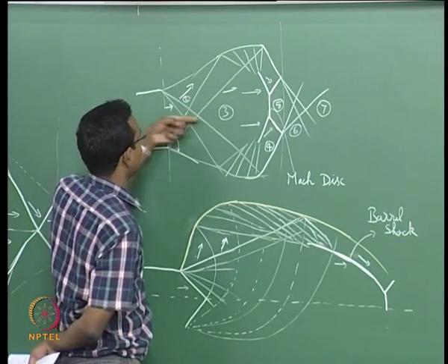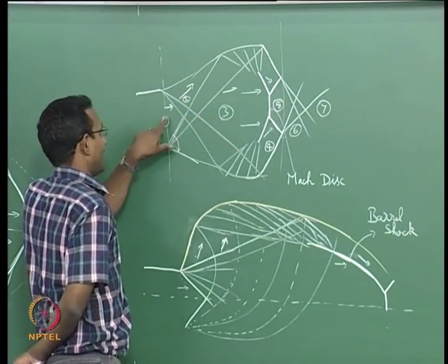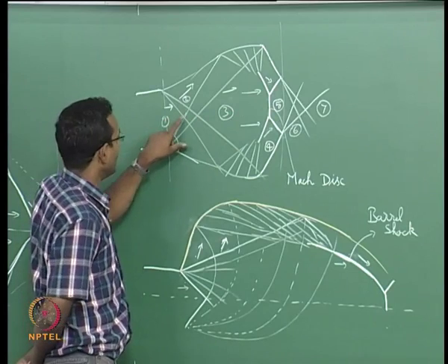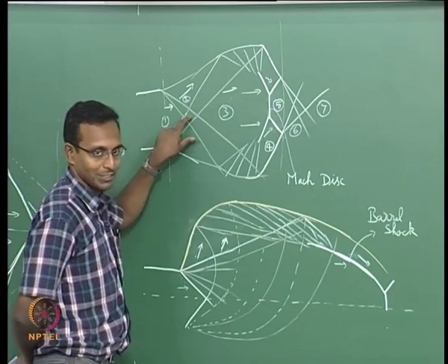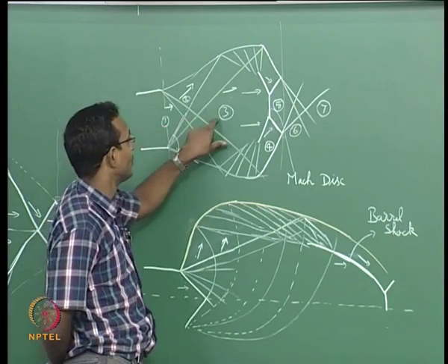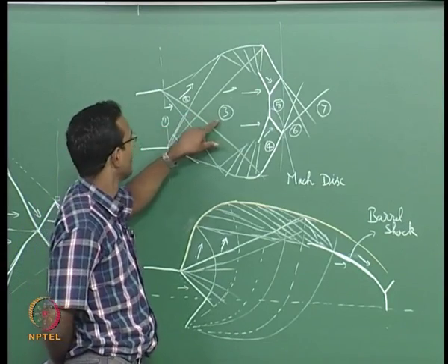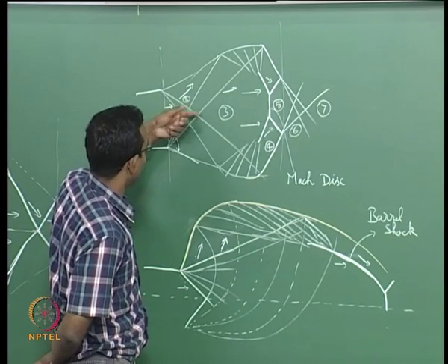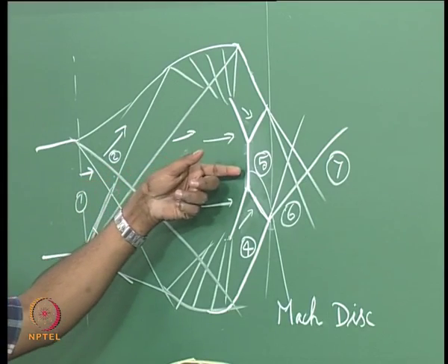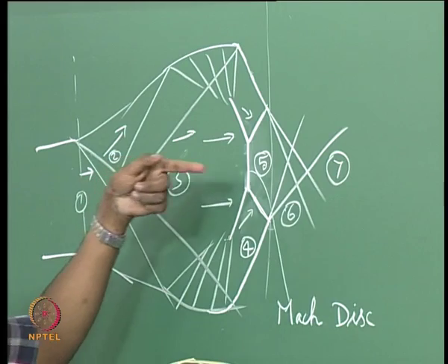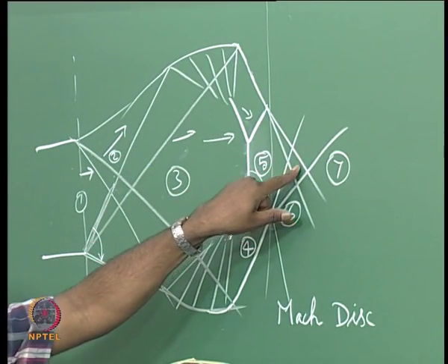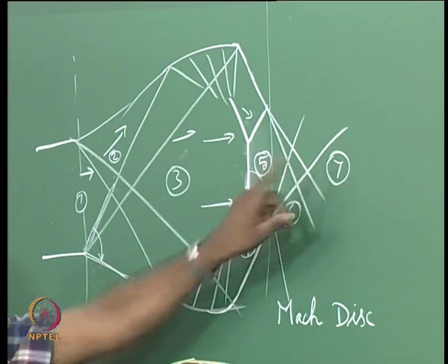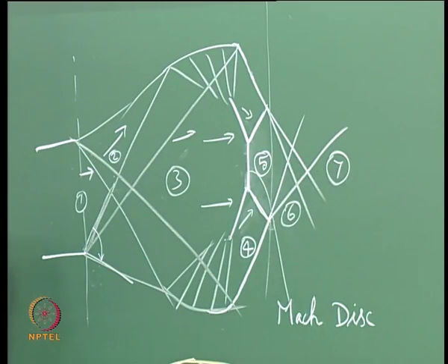If I pick the center line streamline, higher than atmospheric pressure, during the expansion processes inside here, it will cross expansion somewhere at atmospheric pressure, then it will go to lower than atmospheric pressure. High, drops to low, and then stays low, suddenly jumps up to high, and then just stays high, and then it drops to low through this set of expansions, and then it goes low. Like that it just alternates up and down.